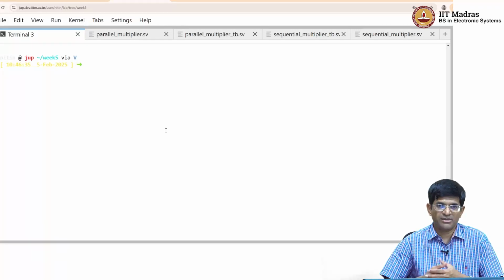It actually forms an important part of an overall design process called OpenROAD, right. OpenROAD and OpenLane are two different projects that were started among universities in the US in order to build up a completely open source based design flow. So, I will be using Yosys primarily to demonstrate how synthesis can happen in the first place, and what we want to do with that is to just look at what the output of synthesis looks like, right.